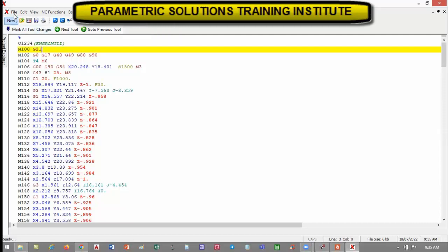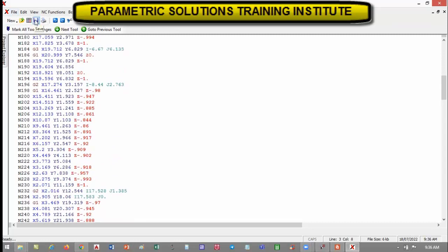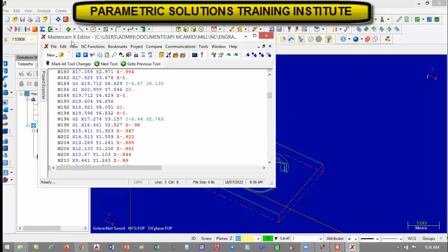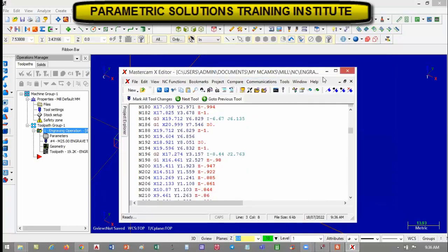Or else you can copy this in a pen drive, and then plug into the CNC machine, and there you have to save it into the CNC machine, and then start the machine settings and operation accordingly. So that comes under the CNC programming and operating.